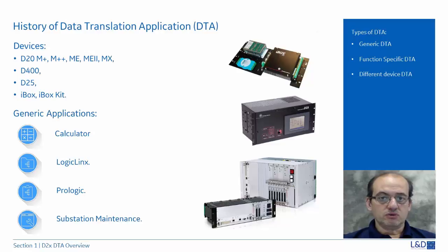Now, what you have to know as a user of the remote terminal unit is that if you're thinking of a certain application or a certain logic, let's say you want to OR all your digital inputs, we could have a DTA that will service your need. For example, the Common Alarm DTA, Data Translation Application. The Common Alarm DTA will allow you to take a whole bunch of digital inputs and change them into a single alarm point.